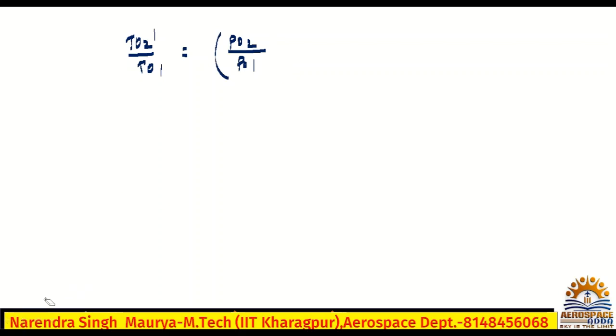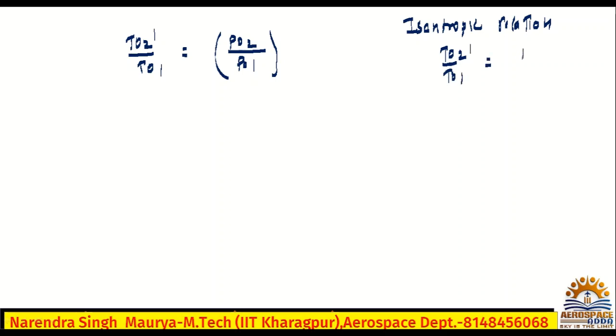T naught 2 dash is the isentropic temperature rise, so you can apply the simple isentropic relation. You can write T naught 2 dash by T naught 1 is equal to P naught 2 dash by P naught 1 to the whole power gamma minus 1 by gamma.